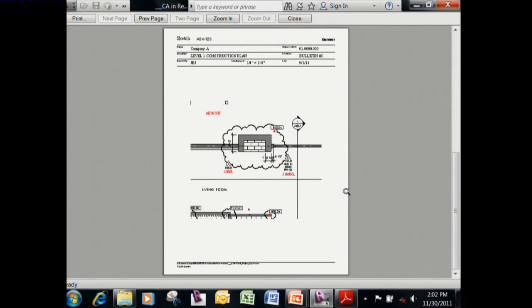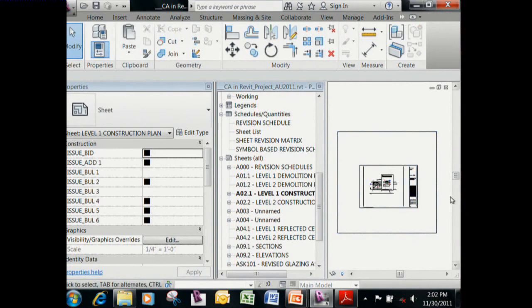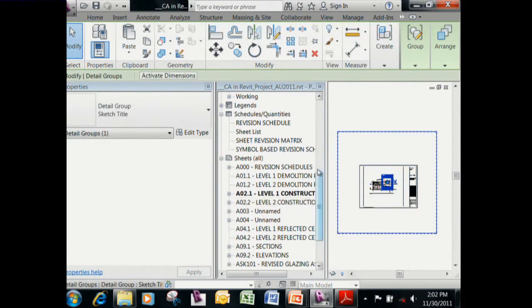So if you try and create one of these yourself, you'll probably get a headache. I think I probably spent a quarter of the time working on this entire presentation dedicated just to trying to get this to work. I know that it is possible to build this into a single family, but you're going to probably run into problems with draw order. And this is something that I hope eventually Autodesk will address and give us some better control over the draw order within families.